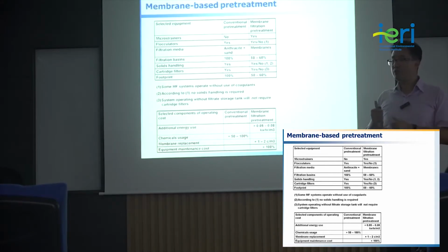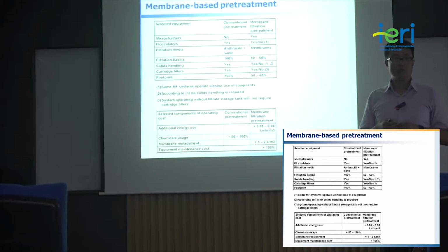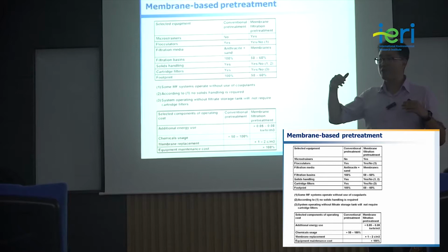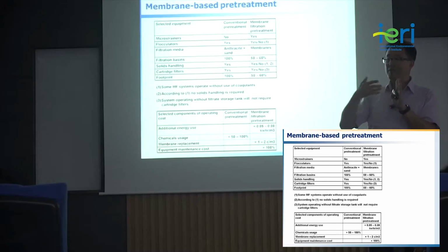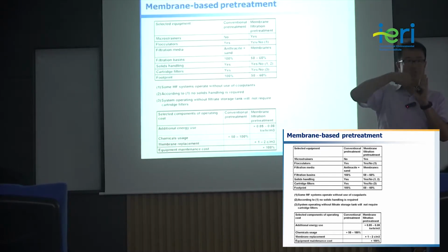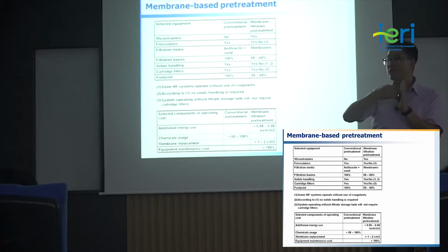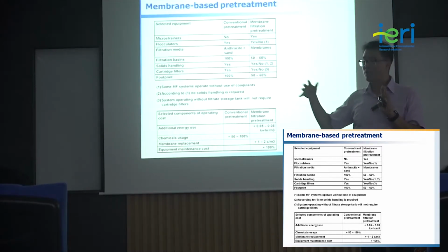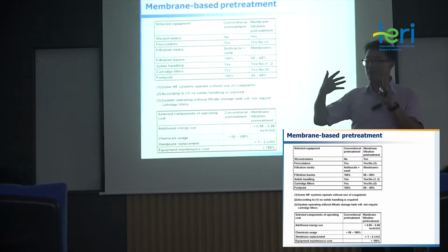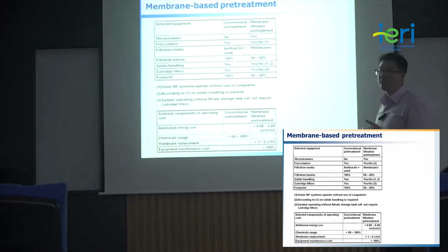So when you design the reverse osmosis membrane, you can put less membrane area, because if water quality is very good, you can design higher flux. If flux is higher, there is more chance of some surface pollution, which we call fouling. You can avoid fouling when you decrease flux. But if the feed water is very clean, it is okay if you put more water. Okay? So that is the advantage of a membrane-based system, but it is expensive.